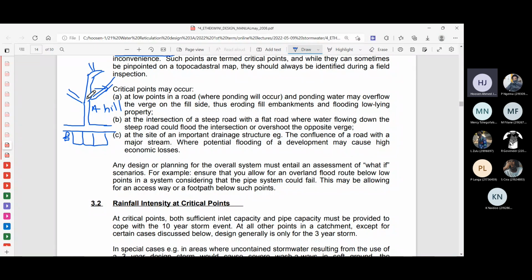So you have a large volume of water coming down the road, because generally we also use our roads as stormwater channels, for transmitting the stormwater into the municipal stormwater systems. So you have a large volume of water coming down, and it's coming down very fast. It will have a high velocity because this is downhill. Remember, this is on a hill, and it will then shoot across.